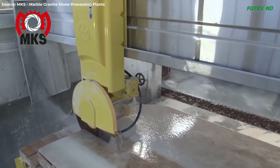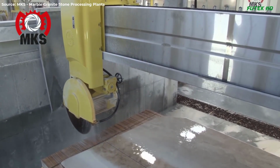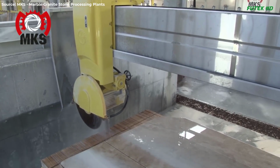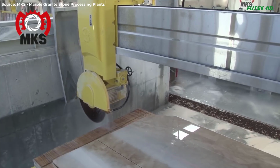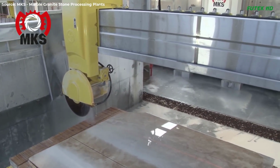The flywheel and the main shaft are connected via a belt and pulley system, which is independently tensioned to maintain power efficiency and reduce unnecessary power consumption. This setup minimizes excessive amperage draw and enhances the machine's operational efficiency.